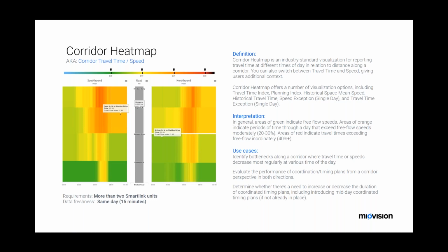So it's a good way to understand where a problem is before you start getting into the timing diagram side or the timing plans itself. You don't necessarily want to go look at two intersections that the travel time is working fairly successfully across. You would want to look at where in the network it is actually breaking down, and that could point to things like coordination problems or offset problems. Could mean that general amount of time is no longer enough.